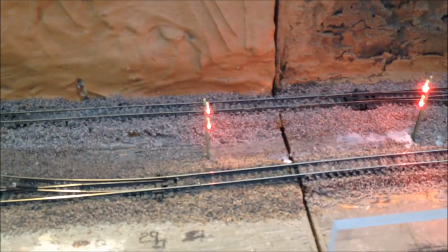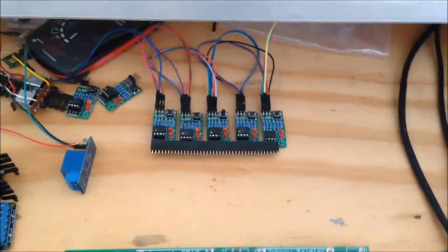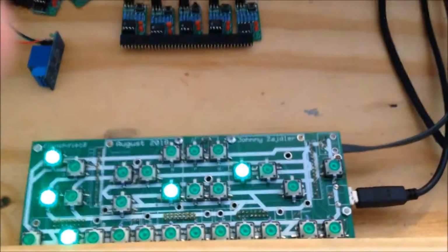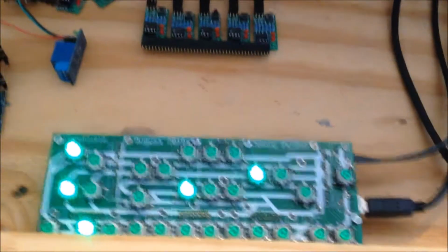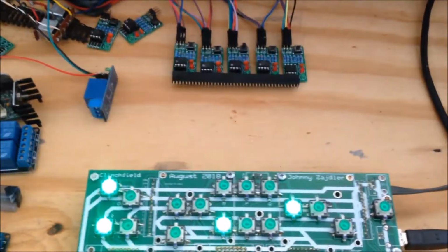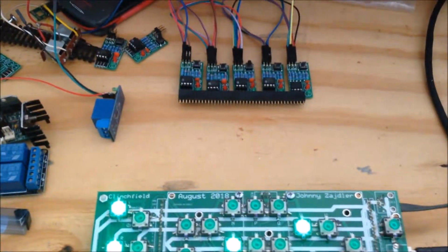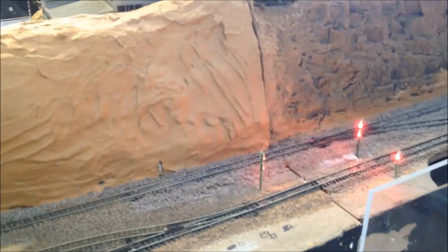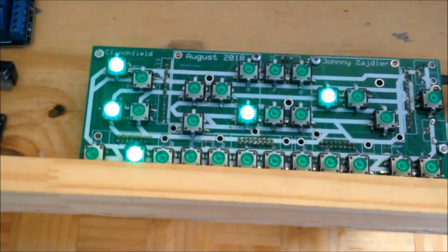These are DCC signals, so they don't give any feedback. But the turnout decoders give feedback, and the block occupancy gives feedback. So based on whether or not the block is occupied, and then you select the turnout, the system will issue not only a LocoNet command but a DCC command to turn the DCC light red, yellow, or green. Each one of those lights has addresses. They're DCC aware, so they have DCC addresses, and that's how they'll respond.